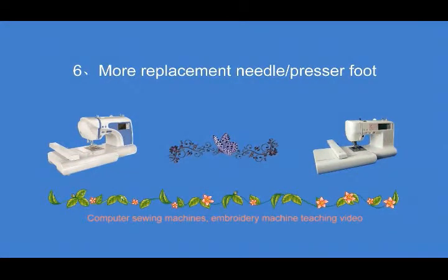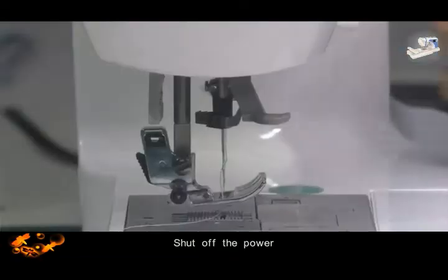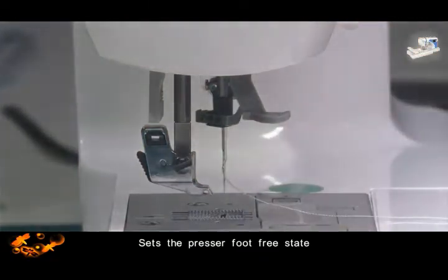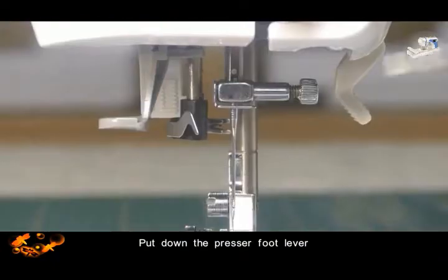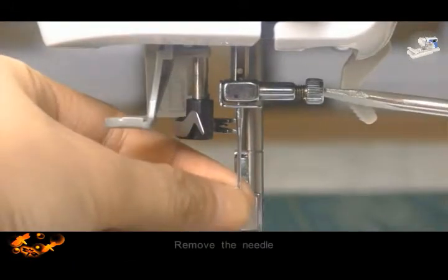Six. Replacing the needle / presser foot. Shut off the power. Press the foot spring switch on the shelf. This sets the presser foot to a free state. When installing, aim at the presser foot rack slot. Put down the presser foot lever. With a screwdriver, loosen the needle fastening screw. Remove the needle.